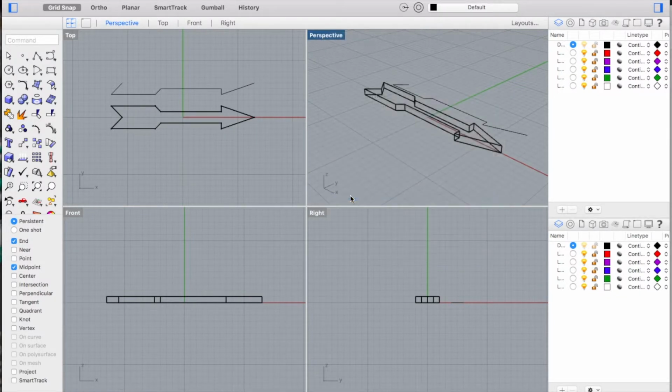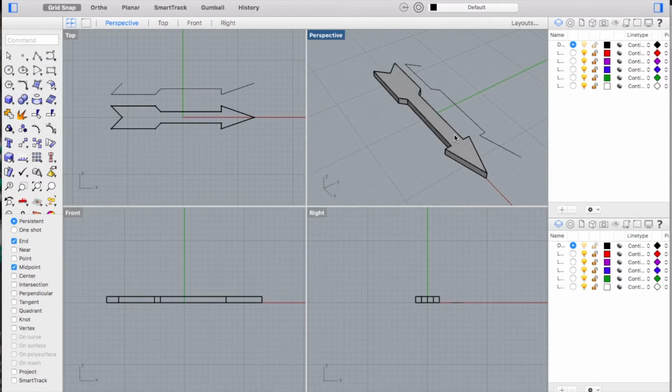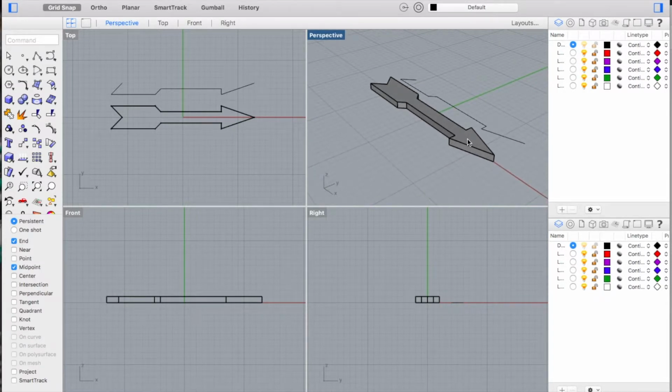And turn it shaded real fast, and now you can see it's 3-dimensional and solid. If yours is not solid, you have a gap, most likely at the 2 connection points where we did the mirror, and you'll have to redo that. It has to be solid.